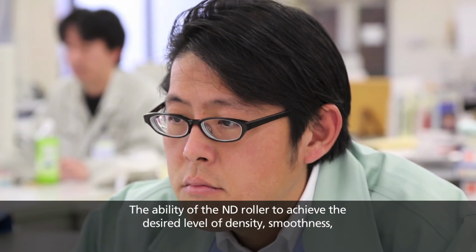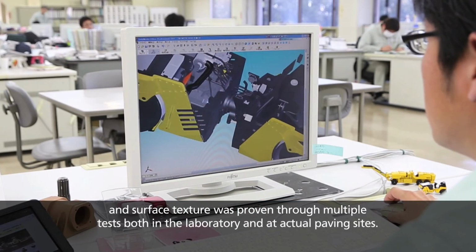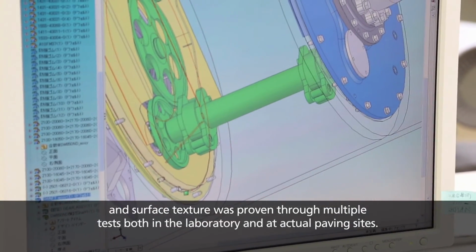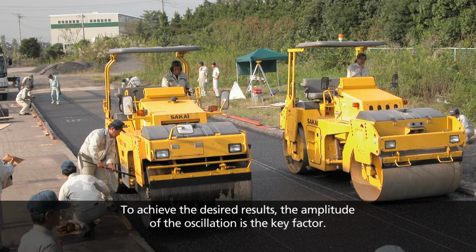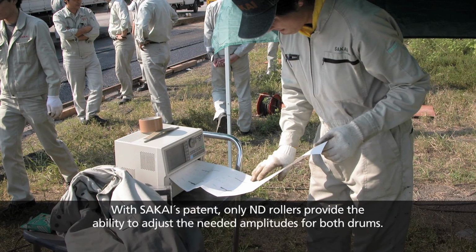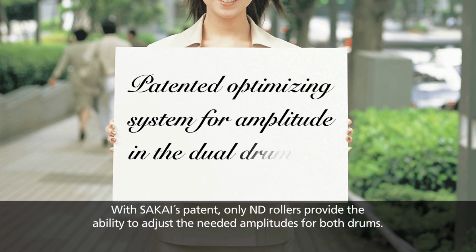The ability of the ND roller to achieve the desired level of density, smoothness, and surface texture was proven through multiple tests both in the laboratory and at actual paving sites. To achieve the desired results, the amplitude of the oscillation is the key factor. With SAKAI's patent, only ND rollers provide the ability to adjust the needed amplitudes for both drums.